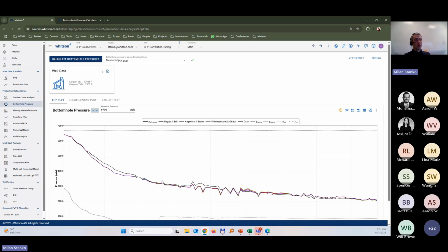Yeah, I don't think so. The way people capture the effect it has in your correlation is that it changes the holdup. So the holdup that you're getting will be something different and will be, let's say, more gassy. It will be less liquid because you trap the liquid in this foam. People modeling that either modify the correlation in some way, and usually it's by changing the surface tension.